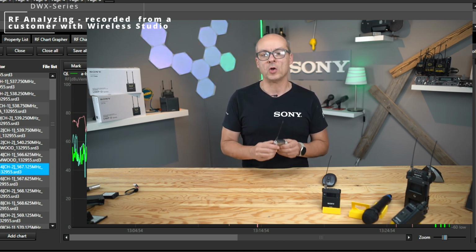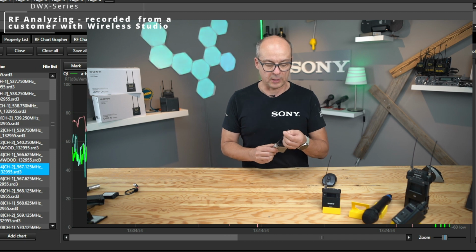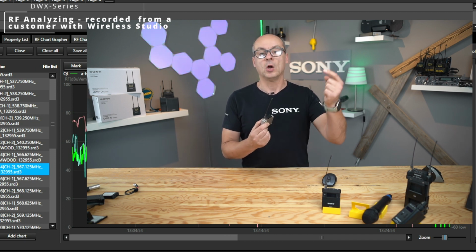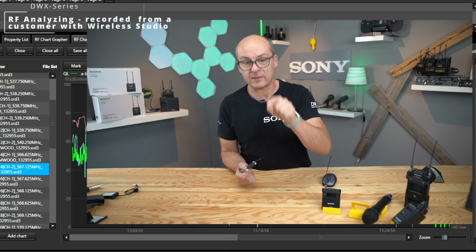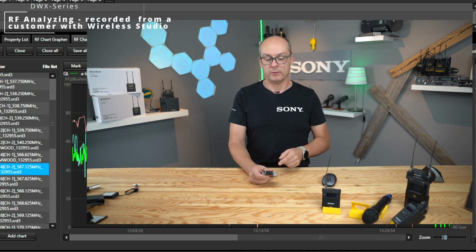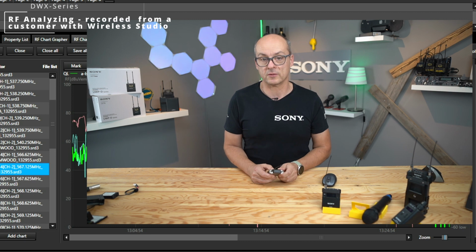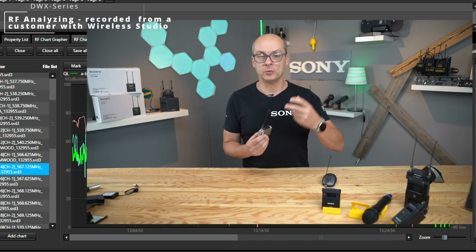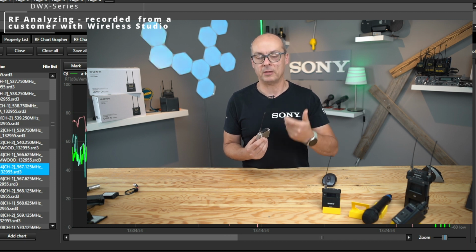Don't do this. The other point is, if your cut is not perfect, then you get reflection inside the antenna cable, which goes back into the amplifier. And that's what happened here, from my point of view, what we see on the screen. So reflections go back and produce interference inside the antenna amplifier.